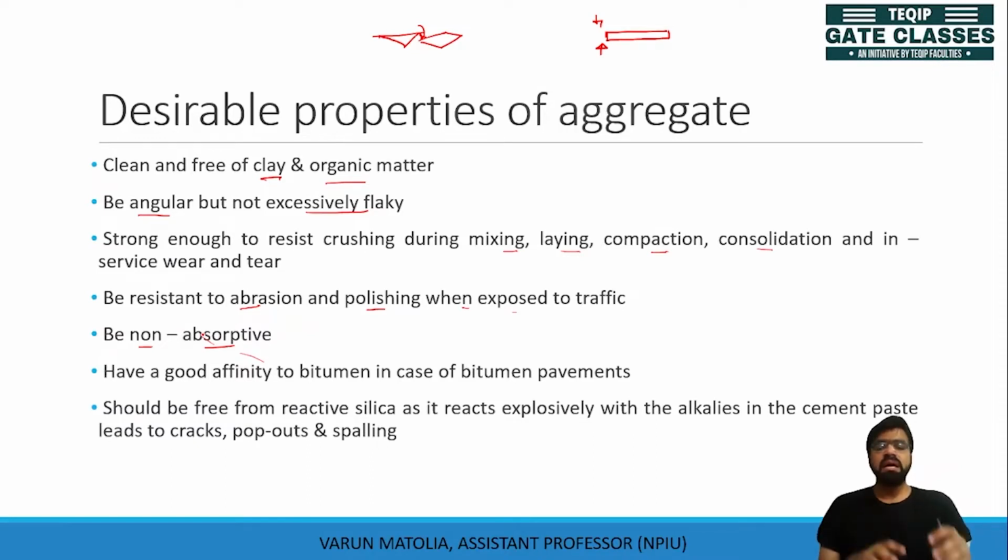Then if they absorb water, they will have less affinity for the bitumen or the binder to bind properly. So for the binder to bind properly, there should be less water or no water present on the aggregates.